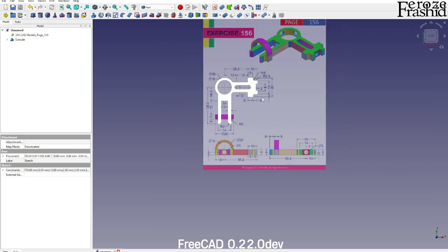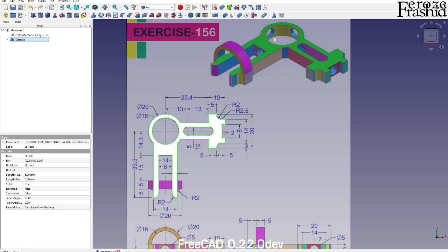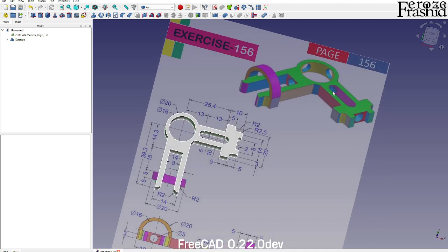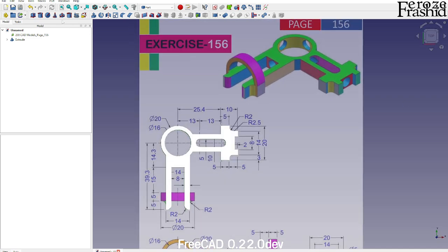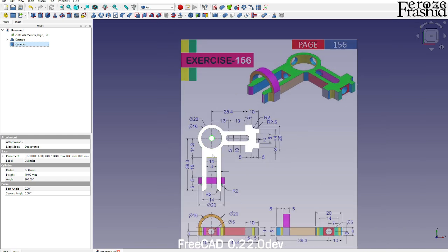Now we got that, right? Then I see these two holes that I'll have to make, and looking at those, I think it will be better to make this symmetric. So that way I can build those cylinders and not think about where they're placing. Okay, the cylinder, and the first one I want to lay down like this. So that would be a long cylinder, let's say 100, right? And then the diameter is 5.